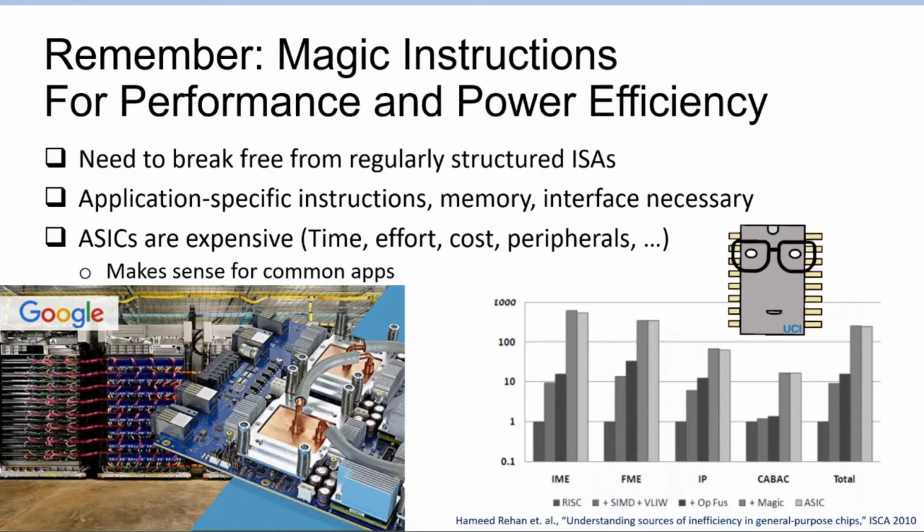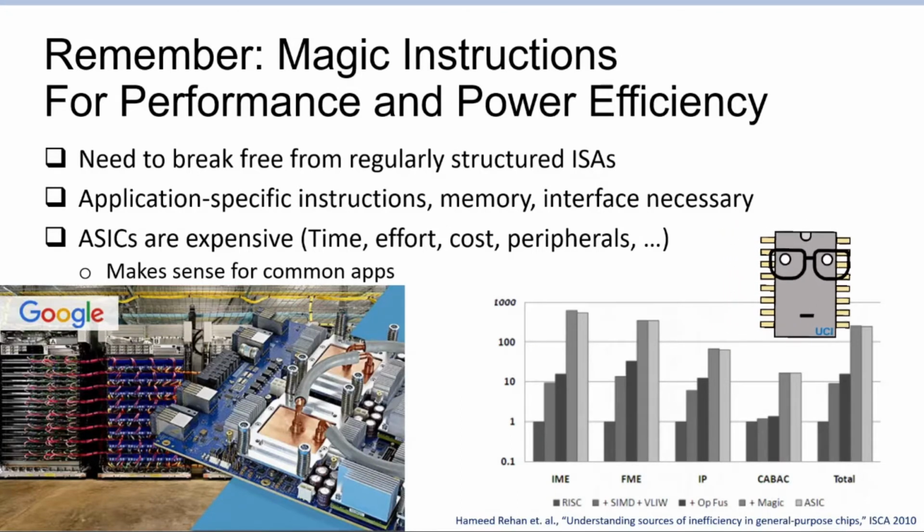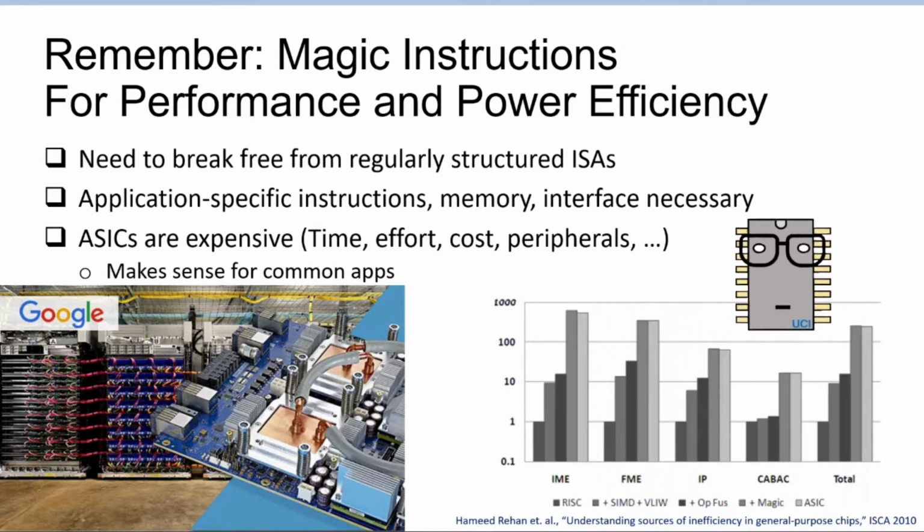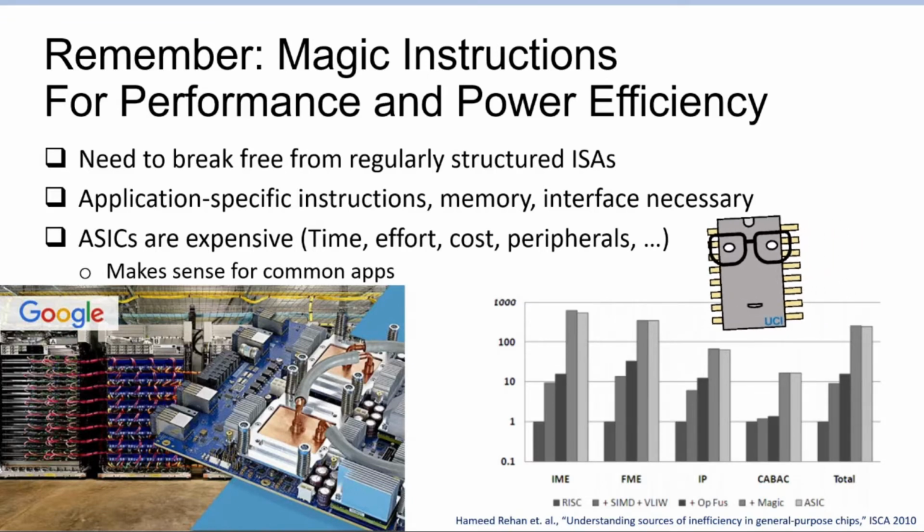And on top of that, in many cases, if your chip has a drastically different interface in terms of which pins do what, your chip isn't going to have the exact same form factor as, say, an x86 processor. It's not going to have the exact same communication interface as an x86 processor. You can't just plug it into a motherboard. So most of the time you will actually have to build a PCB, a printed circuit board, a tailor-made motherboard as well for talking to your ASIC.